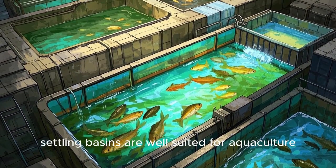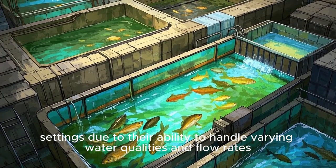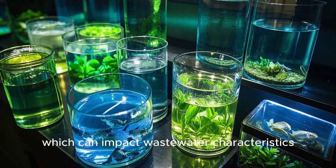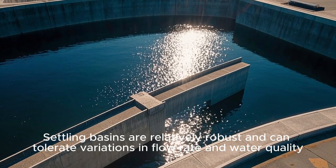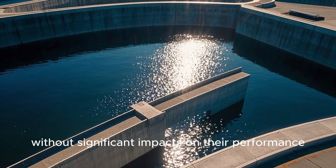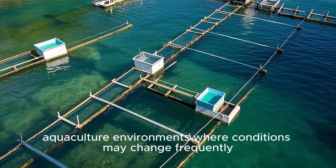Lastly, settling basins are well suited for aquaculture settings due to their ability to handle varying water qualities and flow rates. Aquaculture operations often involve fluctuations in water quality and production levels, which can impact wastewater characteristics. Settling basins are relatively robust and can tolerate variations in flow rate and water quality without significant impacts on their performance. This makes them suitable for use in dynamic aquaculture environments where conditions may change frequently.